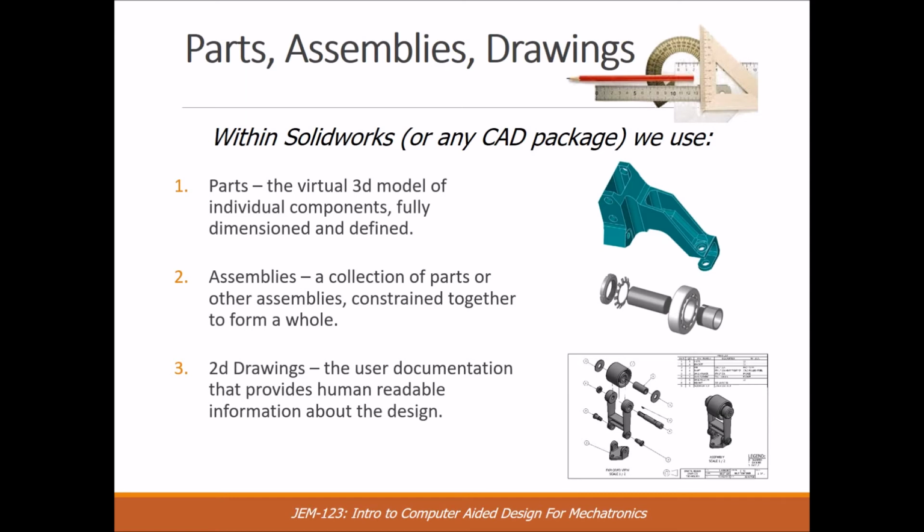You can do, as shown here, an exploded assembly, how things fit together, what the part numbers are, what some of the fits and tolerances are, the proper way that they are meant to be put together, or even the order of assembly. It shows the revision, who you are, the name of your company, other notes and legends.